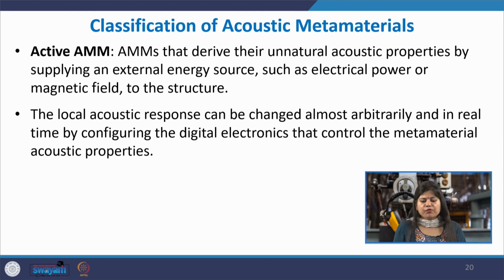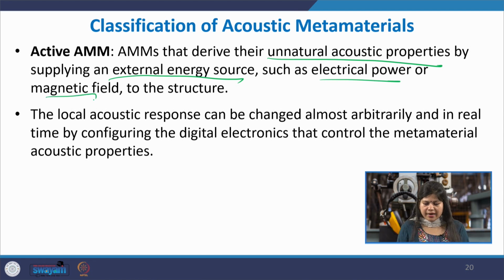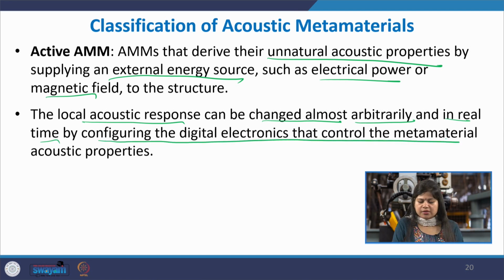Okay, the last type of acoustic metamaterial is the active acoustic metamaterial. Now, they derive their unnatural properties by supplying an external energy source to the structure, and their acoustic response can be tuned or tailored arbitrarily and in real time by configuring the digital electronics that control the metamaterial acoustic properties. So, basically you can have some AMM